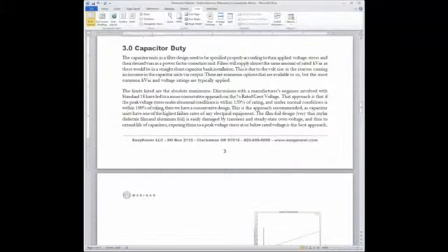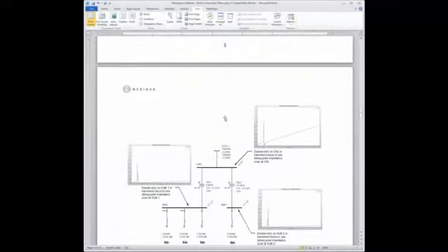Because of that, we specifically used smaller can sizes. We didn't do 400 kVAR, which would have been nice, but it would have been really difficult for them to get those out of the banks. So what we chose was a smaller 200 kVAR so that at least they could possibly lift it out with the help of a small crane. The cans get really heavy the bigger they get, especially if they're oil impregnated.